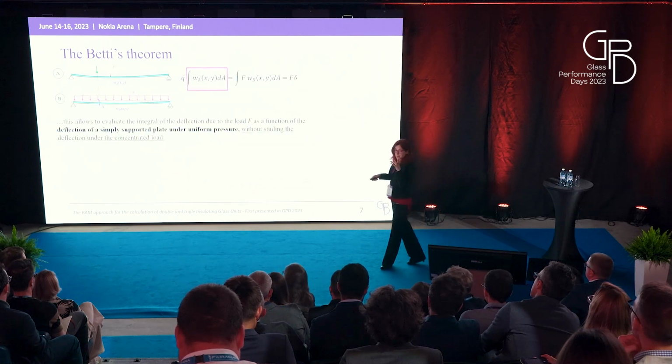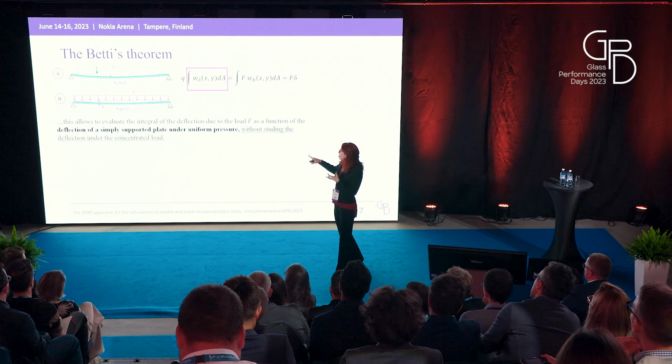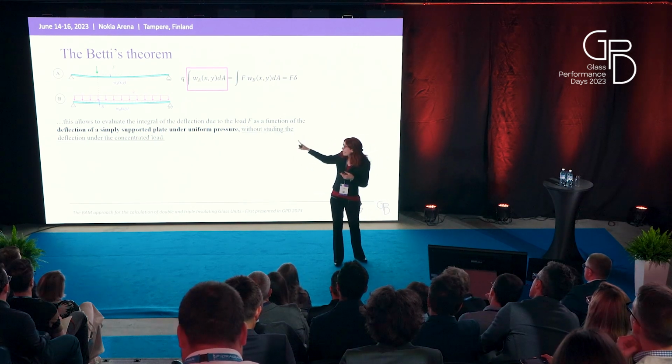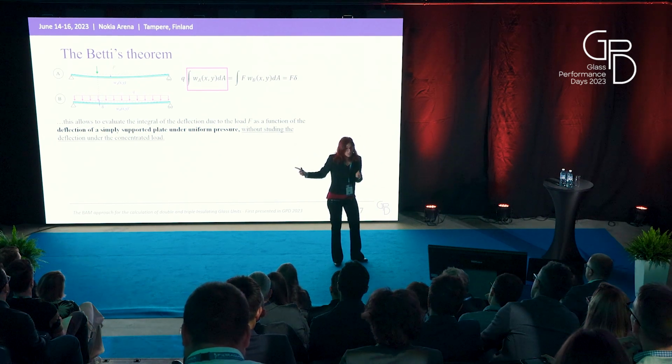And this is a remarkable result because it allows us to evaluate the integral of the deflection due to a concentrated load without studying the deflection of the plate under a concentrated load.